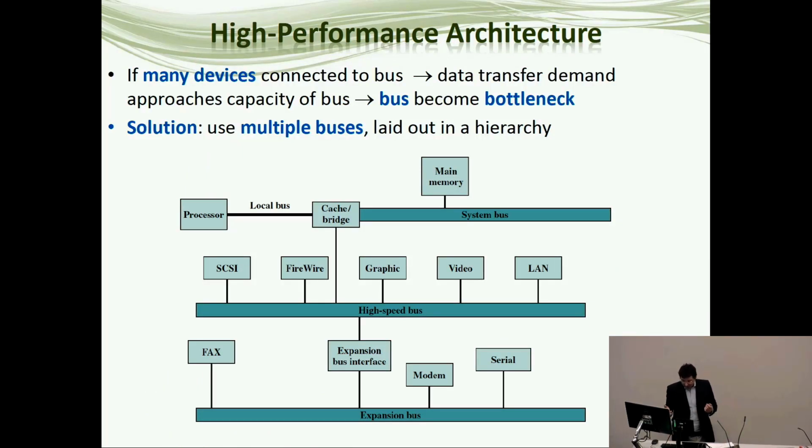So in the 8-bit era, there was usually only one bus as well. It would come out of the CPU, it would go to the RAM, the ROM, the I/O modules. Nowadays, we're moving to these hierarchical bus architectures. In some cases, you might have 3 or more buses now.